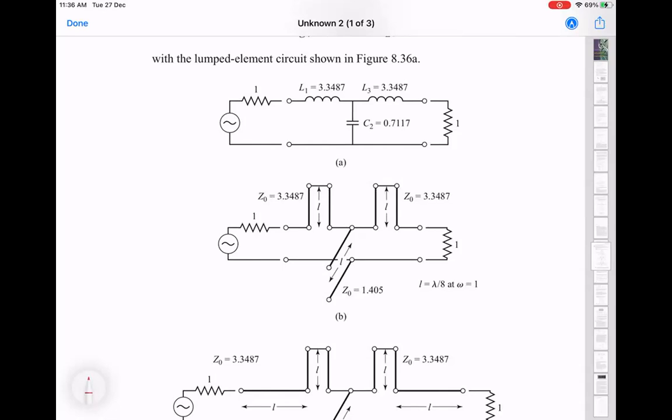You have two things you can control with the transmission line: the length and the characteristic impedance, and maybe the boundary condition. Okay, three things. So once you make the mapping, if you do it for equiripple, then you'll get the equiripple response but only in that specified band of operation. You will see that it will repeat again in the same way later on.